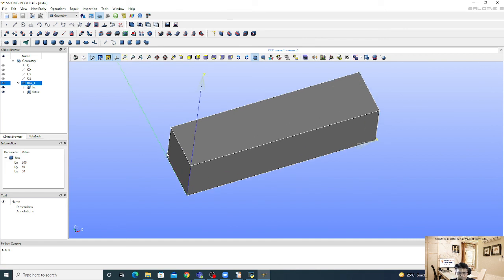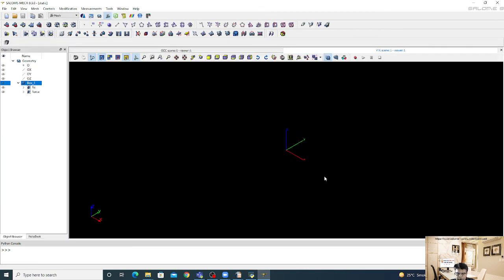So I believe that the geometry part is over, because we are not going to define custom meshing sizes. We are going to choose whatever mesh the software creates. Then we will move to meshing. Now remember that the geometry groups we have created are only for that module. They don't belong to the meshing yet, because we haven't created the mesh yet.